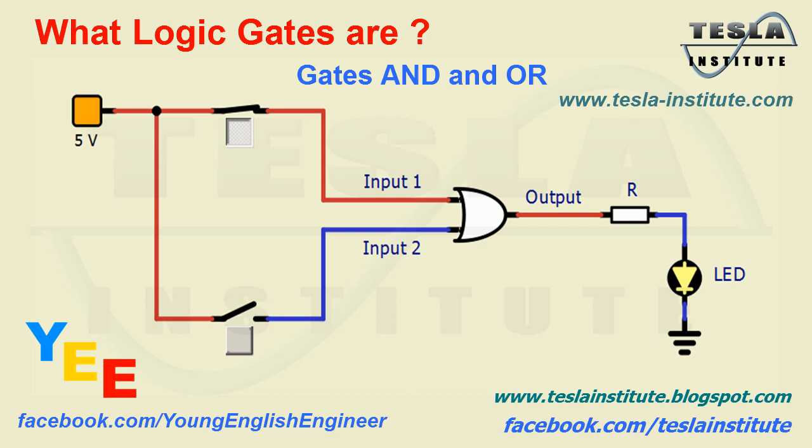And this is because it's an OR gate, so for an output from our logic gate, we only need a logic high, or one of the inputs, to be active. So input 1 or input 2 can be active. What about if we activate both of them? Nothing changes, because one of them is still active. It's an OR gate, so it doesn't matter if both of them are active. It's just if one of them is active, then we get a logic output. If we disable both of them, neither channel 1 or channel 2 is active, so we don't get an output.